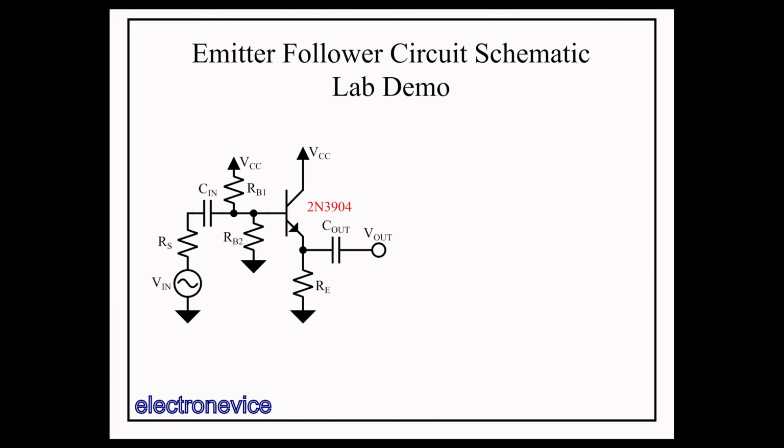This is due to the fact that input buffers add noise, and in order to incorporate a low noise buffer on the input of an ADC, it requires additional power and cost. With greater power and cost, the lower in noise you can go. So most ADCs leave it to the user to put their own buffering circuitry there, depending upon their needs. Users that require ultra-low noise inputs, and to whom cost is no object, will put expensive, power-hungry buffers. Users that don't really care about the noise level will put a cheap, low-power buffer or use none at all, accepting the resulting noise or errors.